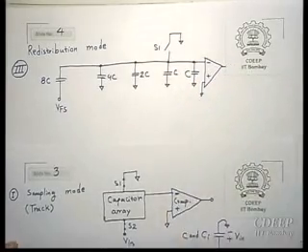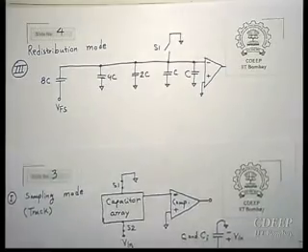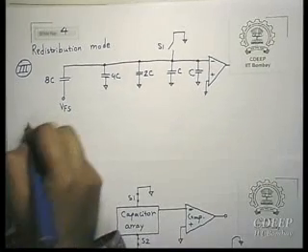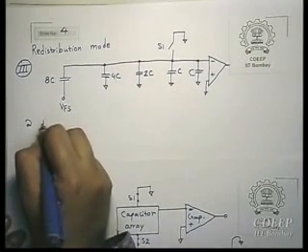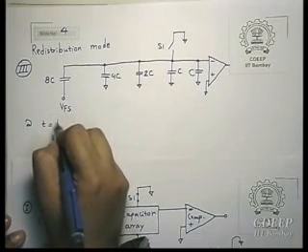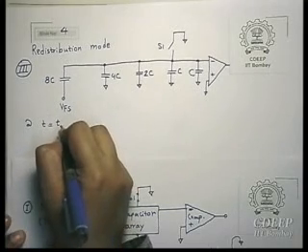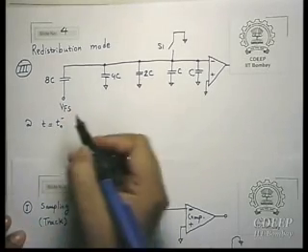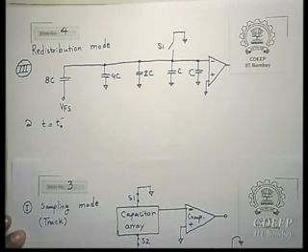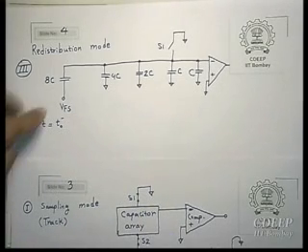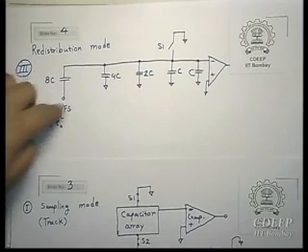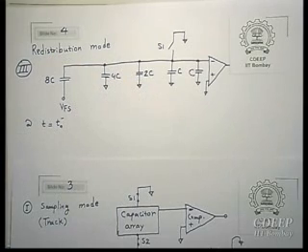Now what will happen? So let's draw the equivalent circuit. By the way, we know that at t equal to T0 minus, we had Vin on all capacitors. So what is T0? T0 is exactly the time when we connect the bottom plate of 8C to V full scale and the others to ground.